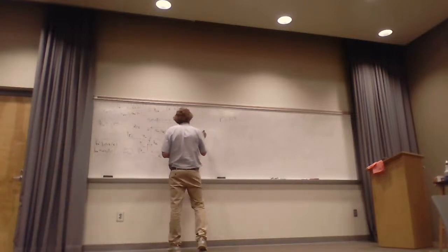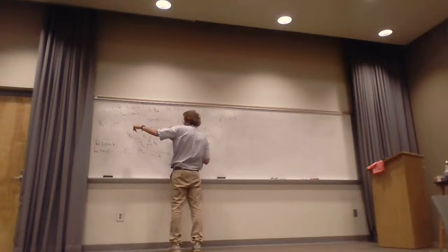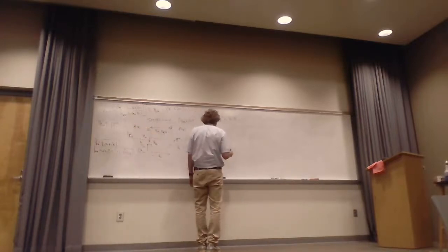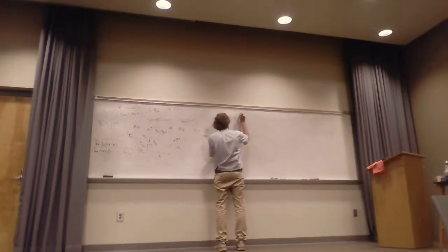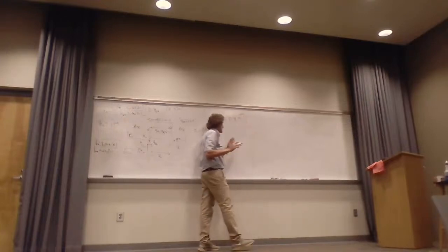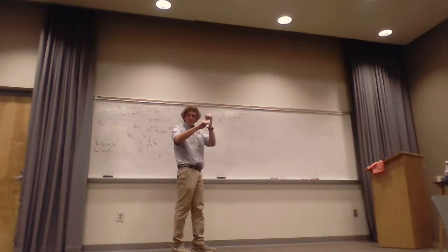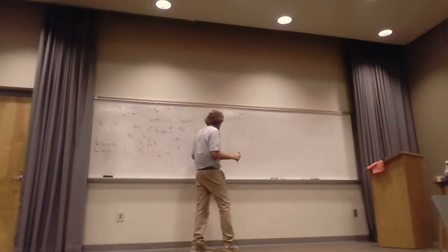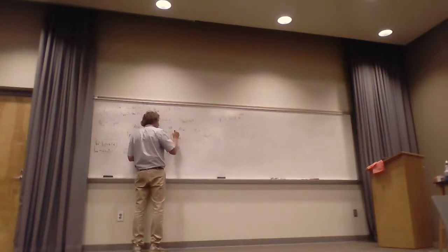So here I say the transmission coefficient in region 1 is 2 times eta shield over eta shield plus eta naught. It's coming from air, so it's eta naught. I'll leave that there. Then it will decay as e to the minus alpha z. Now this is strictly magnitude I'm worried about, not phase. Y'all follow me? As it's propagating through the shield, it's decaying, right? It's because it's a lossy material, so it's going to decay. Then it's going to hit this side, and there's going to be a second transmission coefficient.